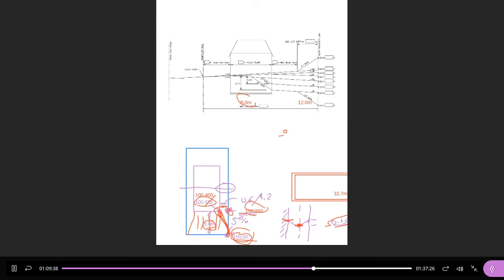If you're negative 0.58 lower at the back, your split point would be at the front of the building. If you have a difference between front and back between those two numbers, positive 0.15 and negative 0.58, then you would come up from the front at 2% and come up from the back at either 2 or 3%.